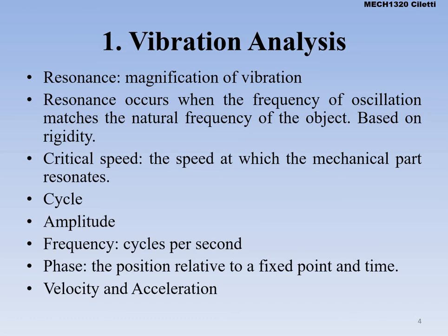We take a look at its cycle, its amplitude, and those are what we looked at in the electrical class when we look at cycle and amplitude and things like that, right? We know that when we're talking about vibration analysis, we're looking at a sinusoidal type wave, all right? So we can see some sort of pattern. Is it out of the norm? And is the frequency changing, right? Remember, frequency is cycles per second. We talked about that in hertz and that sort of thing. Or the phase, okay, has it shifted as it's rotating around? Or has the velocity or the speed and the acceleration changed? So those are all different mechanisms that we can use to read vibration analysis.